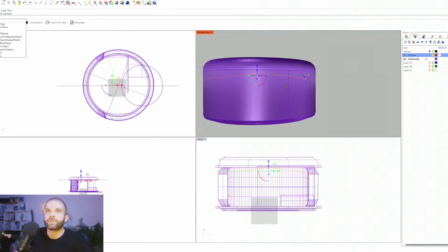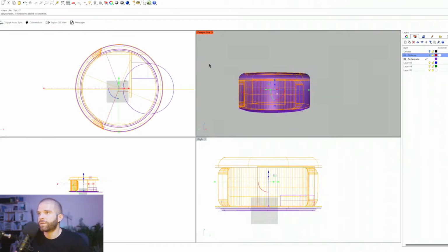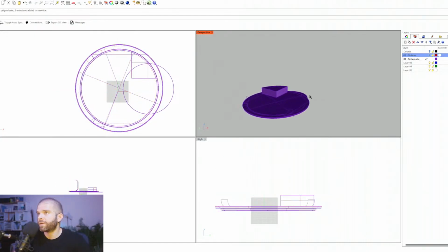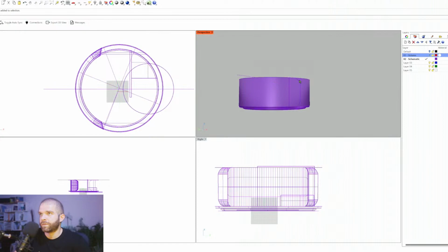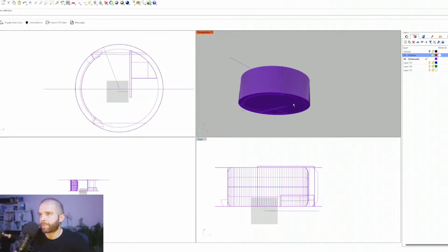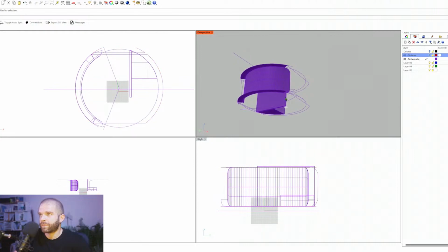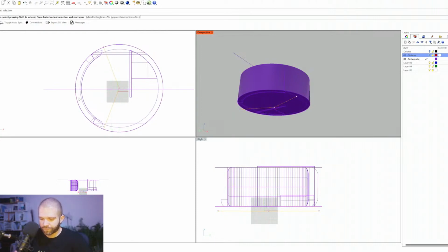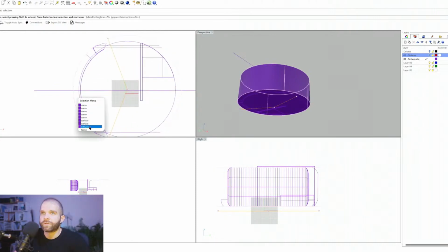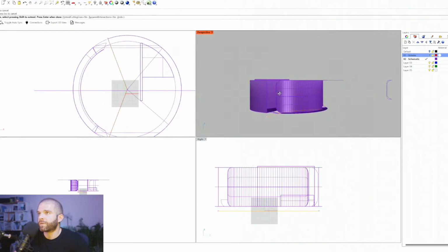I'm gonna project to the ground, or project to Z-plane, just to kind of create that slice. Delete object input, yes. And from top view, I'm gonna hide everything except that one cylinder. Hide, hide, hide. Okay. And now I'm going to use these to trim out this part of the cylinder. Okay.